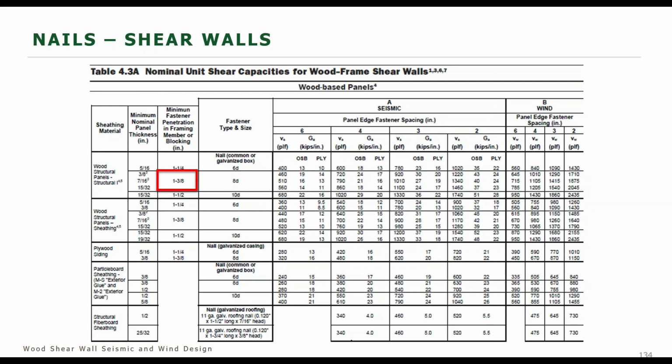And we've heard in the industry that perhaps they may switch out nails. They meet the diameter requirements of an 8-penny, and they meet the minimum penetration. If that's the case, these tables are not applicable because they are not meeting the common nail requirement, which is longer than 1 3/8, or the galvanized box nail.